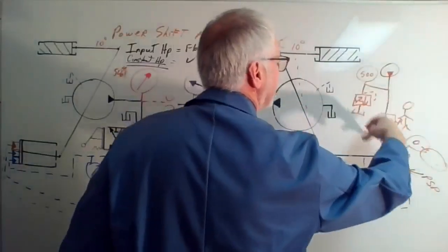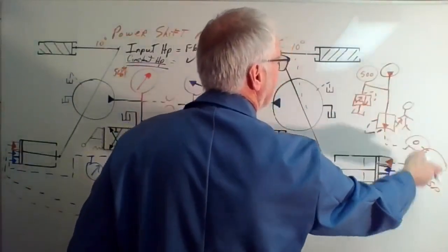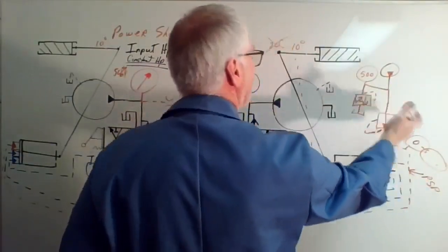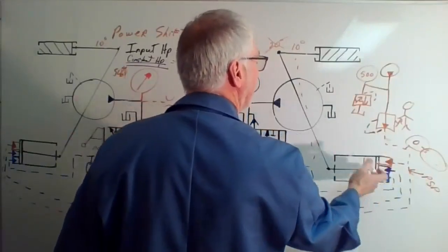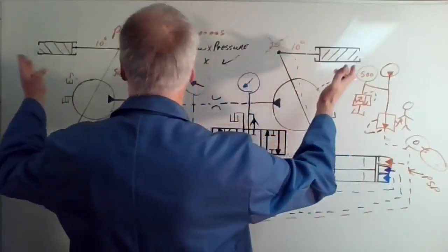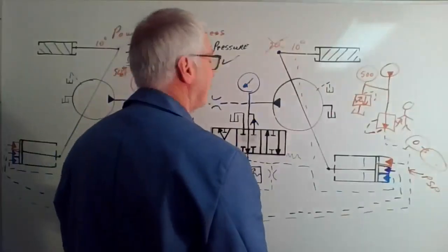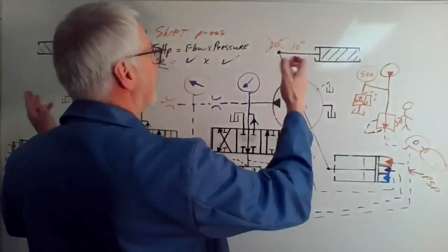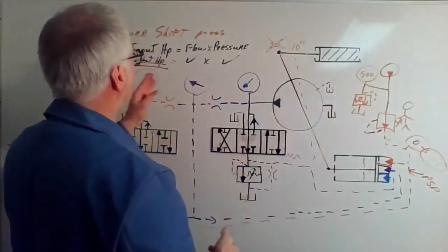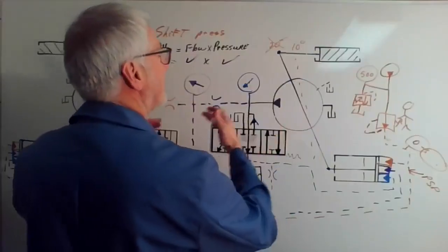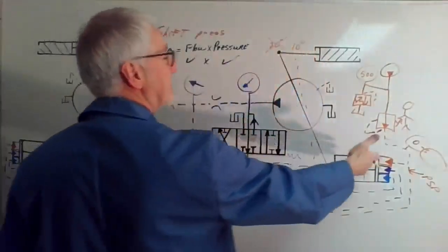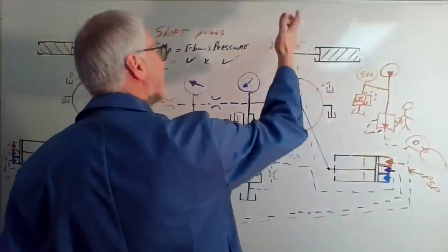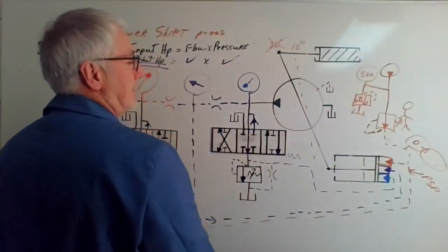Or the operator can say, I want to turn down the constant horsepower, so I want to slow this machine down. And so now the pumps are only capable of a maximum swash plate angle of 10. And it'll run at that maximum swash plate angle of 10, and the cross-sensing pressure will vary it infinitely from minimal to maximum 10 degrees, because the power shift pressure is limiting whatever the constant will be.